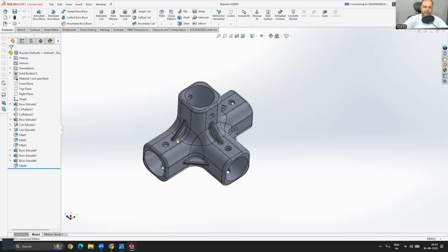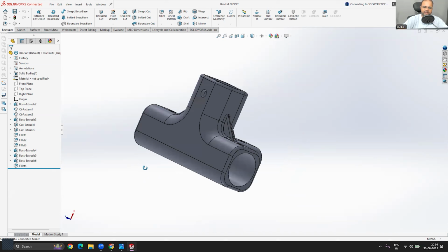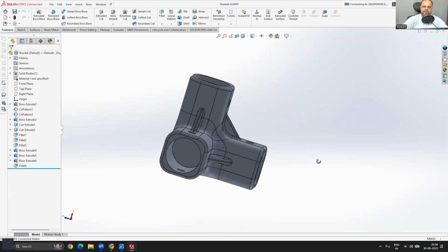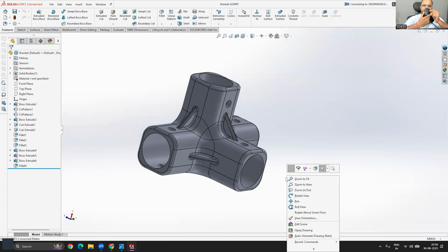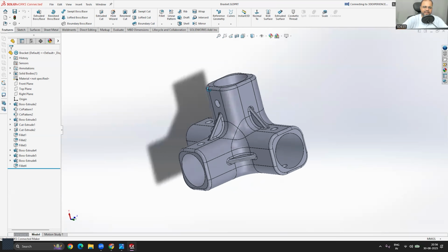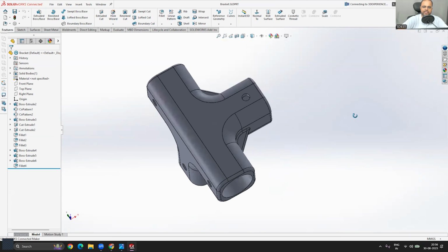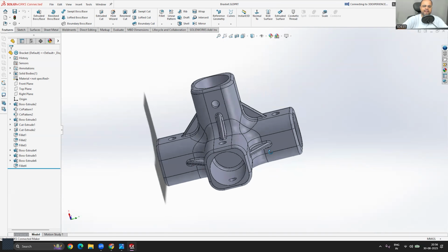Now, I told you how to zoom in and zoom out, right? Now, how you can orbit across your 3D model like this, so you can inspect it from different directions. You can do that just by pressing the middle mouse button of your external mouse. This is the scroll wheel. You just have to press it. So that scroll also works as a button, right? Keep pressing it, and if you move it while pressing, you will be able to orbit across your 3D model. So that is the shortcut for orbiting your model inside SolidWorks.